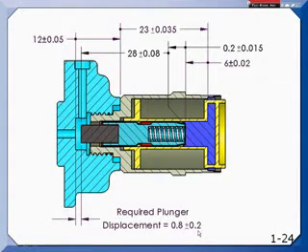Now what that means is I have to take this 0.2 millimeters, and that's my budget. I have to budget that out to all of the vectors here so that I don't get a tolerance accumulation of more than that 0.2. If I have more vectors, each one of them is going to get less tolerance.